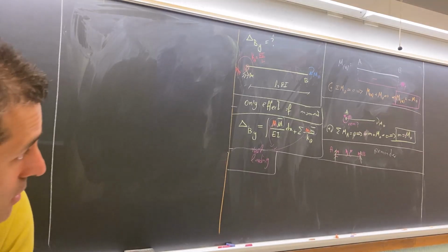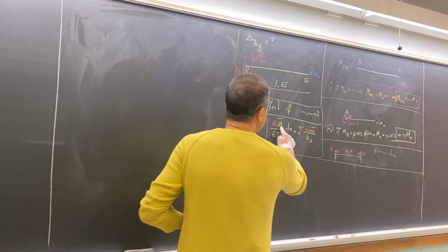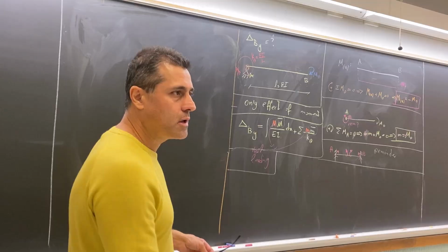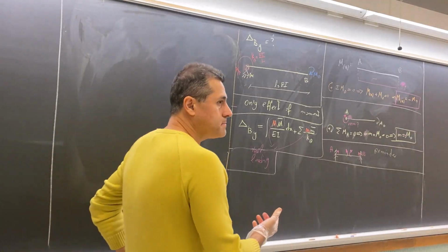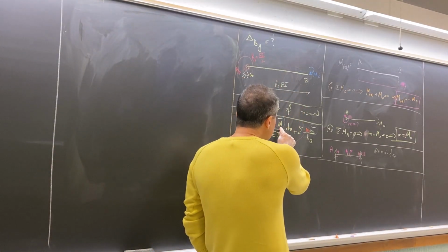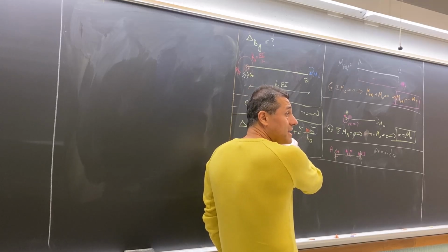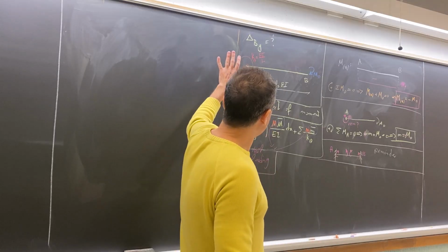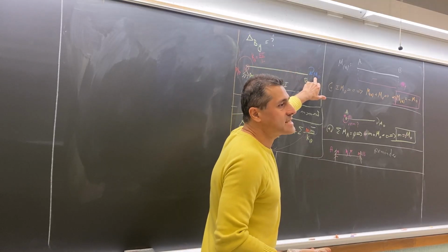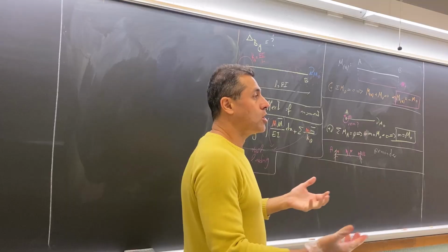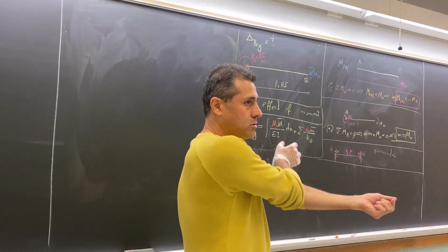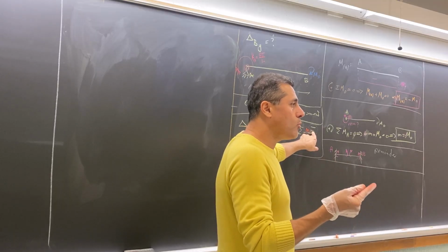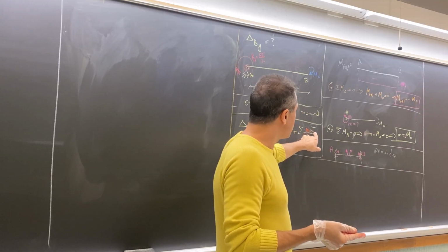Okay, so now we go to these two. What is the meaning of the bar here, Clem? When you put a bar, it means it is virtual. So it means this one is the equation of the bending moment in the same way, but forget about all these loadings. We just apply our own virtual load. And this is the same, the amount of moment in the torsional spring when we have virtual loading.